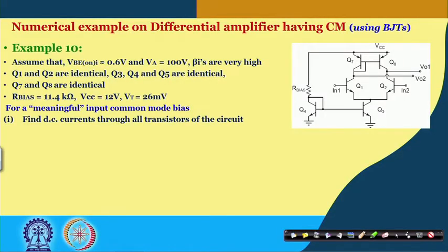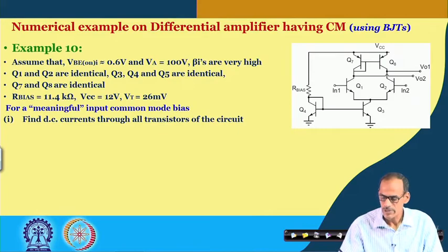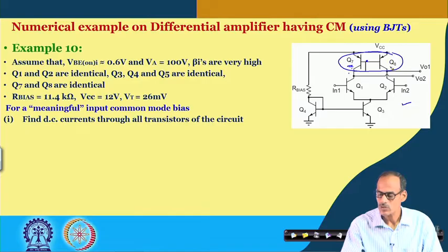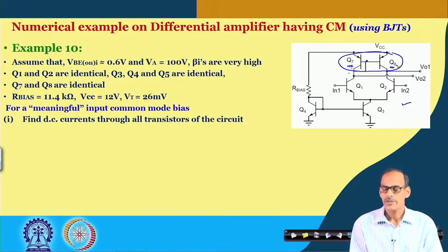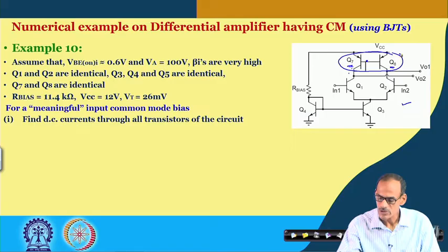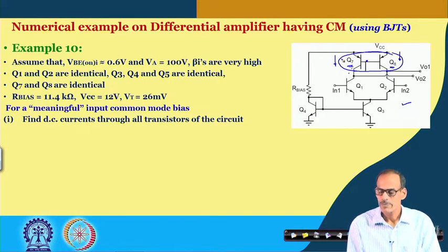Yeah, welcome back to our next example. So, here we do have the differential amplifier and the load, of course, it is active load, but internally we do have current mirror. So, what we are expecting here is that transistor 7, DC wise, will be mirroring its own DC current into transistor 8, and that is good.